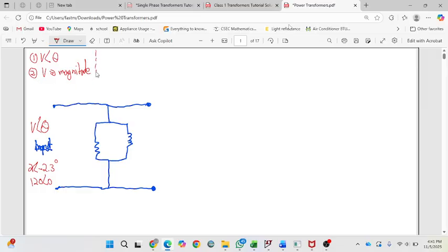The other thing we get into with this circuit, right? When you have your voltage being sent into the system itself, you have this first current here. This current is called I_N, which is your input current, right? This is before any losses in the circuit or your no load losses, and by extension, the current actually going into the coil of the transformer itself. So this I_N is before everything. Some people just mix these things up.